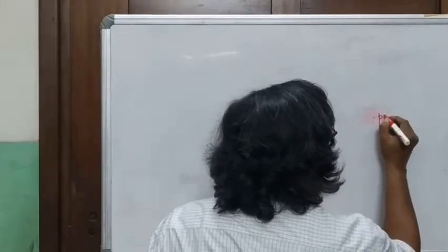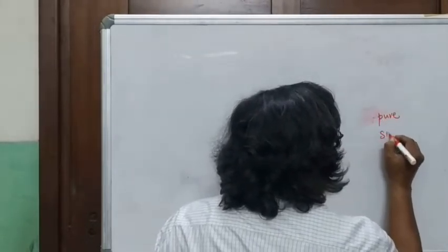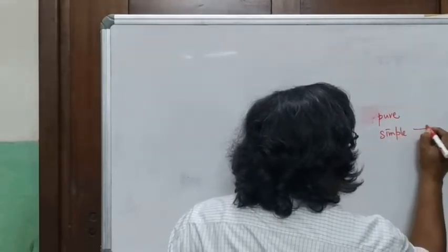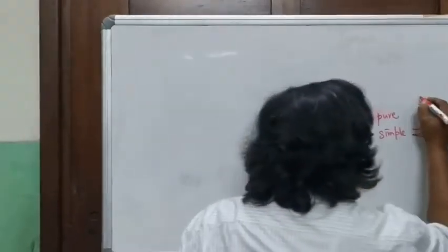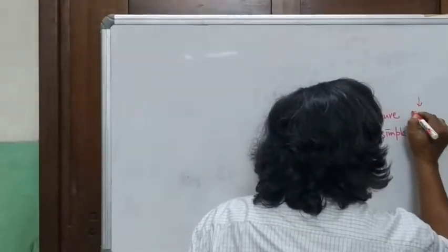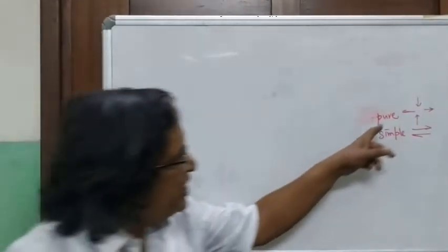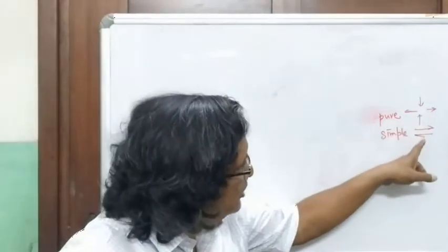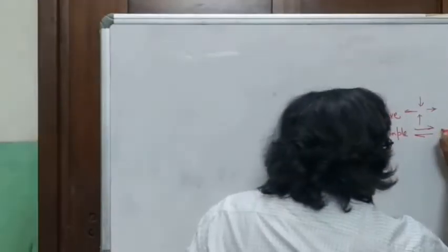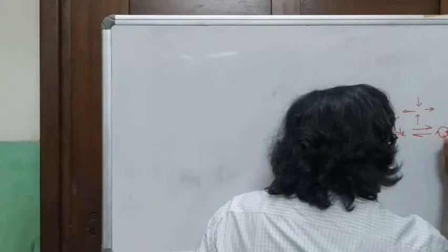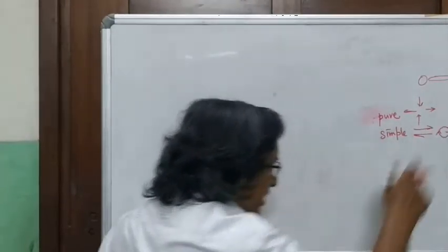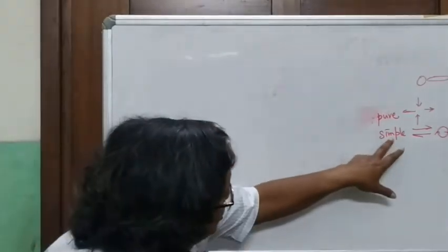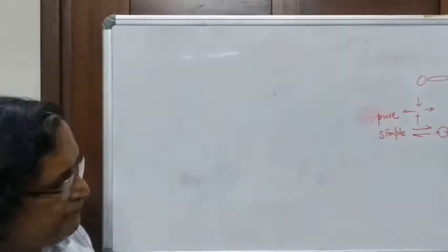Deformation is divided into pure shear and simple shear. Simple shear means moving a pack of cards, shearing. And pure shear is where you have this situation. I told you before also, non-rotational shear and rotational shear. Here there is rotation around this. Here there is no rotation. A circle becomes an ellipse. Here there is rotation. So this is a rotational shear, this is a non-rotational shear.